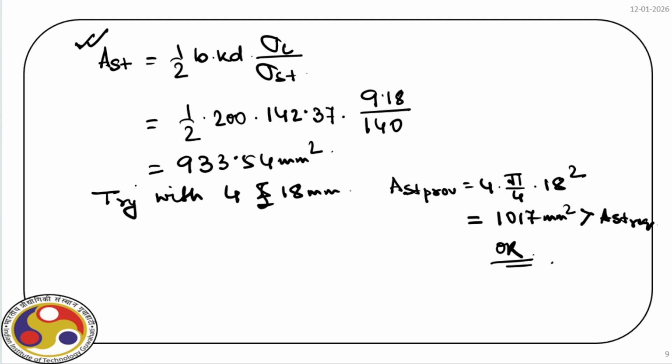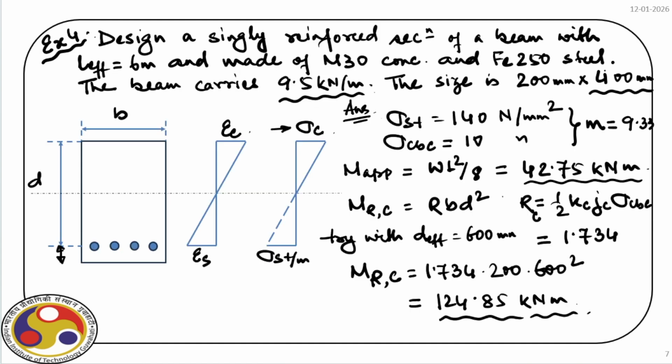That clearly tells you, if we start with a complete geometry, how to find out the moment of resistance at a particular section, and if we know the applied bending moment, and start with the geometry, then we can find out the amount of steel that we need to provide, which is actually the main objective of our RC design. For this problem, I have already explained that you cannot arbitrarily provide any depth.